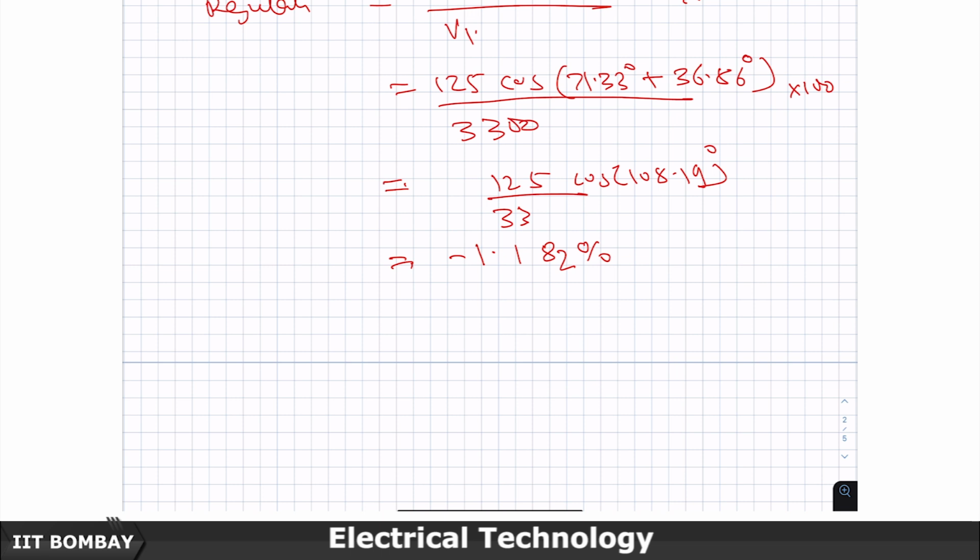So, what this is showing is that if the load has a leading power factor, then the voltage can rise on the load side with respect to the source side. This looks non-intuitive, but this is the way it is. That is why inductance tends to drop the voltage in general, and to compensate for it we use a leading power factor or capacitance to improve the voltage.